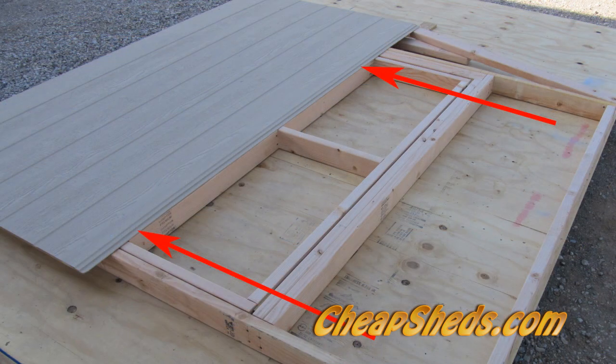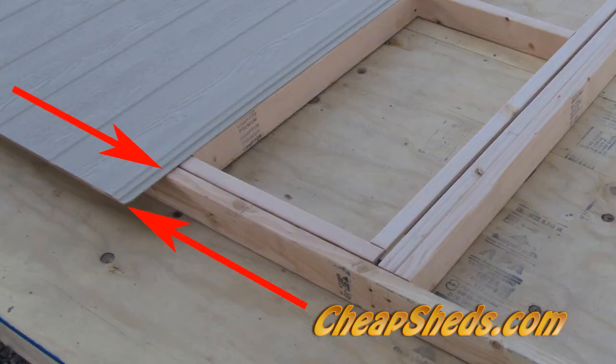Lay the first piece of siding in place. Square it up to the center stud and check for a proper overhang at the bottom.